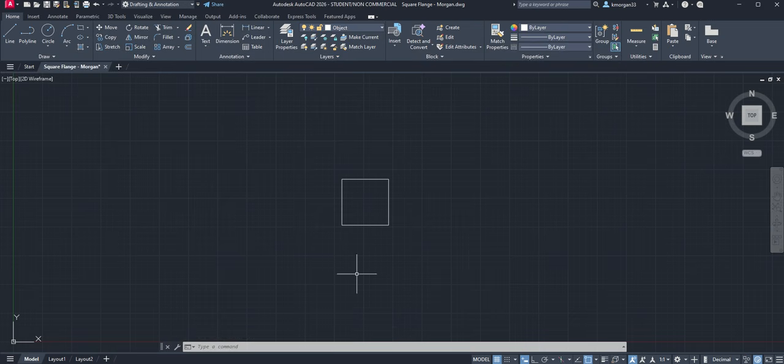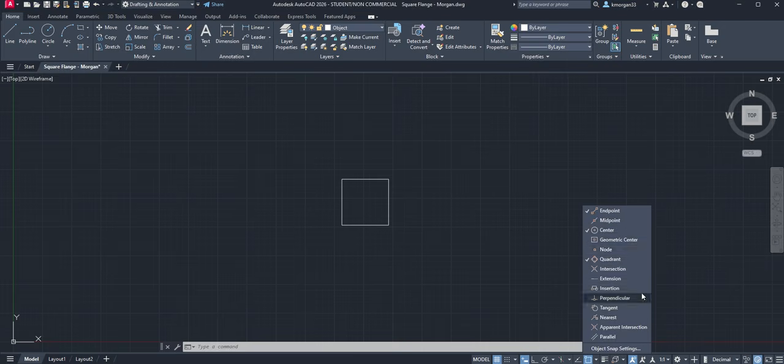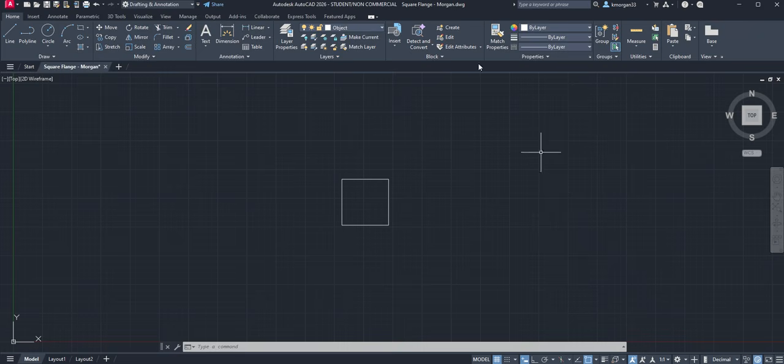Make sure you practice how to input the rectangle. Before we draw the center, what you need to do is make sure you have set up your object snaps. So you have endpoint, center, and quadrants. The object snaps are on, and that is a good thing.